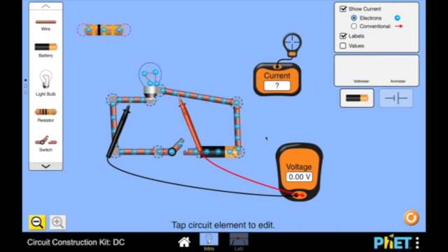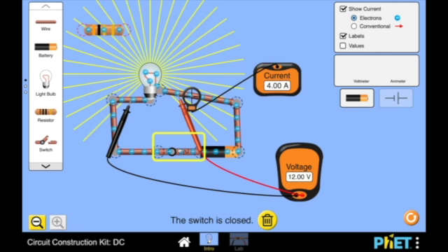So if you're doing some quick math here, you might determine, and I'm just going to grab our little crosshair here to put this over on this side. Right now it's not reading any amps because our circuit is open, but as soon as we close it, remember the equation, voltage divided by the resistance. So this would be 12 divided by 3. What is your prediction? Are you ready? Well, let's see. Let's close it. And sure enough, we end up having 4 amps.